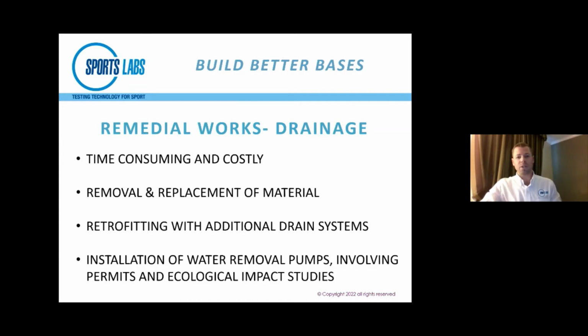So now what do you do? Instead of ripping it up, you have a couple options here. You can remove all this material and replace it, or it involves installing side drains, which means now you're digging up a field that's supposed to be finished. And then you have all sorts of new problems where you've got to recheck for planarity, recheck for compaction, and in some of the worst cases, fields that have been installed in a drainage basin, it could involve installation of sump pumps, things like that.